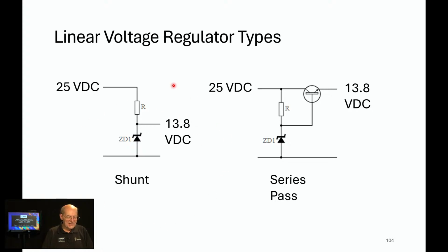Well, yeah, and Kessler's material, he says that, and he's right, for this to work with a 100-watt transceiver, we're talking about a transceiver needing about 25 amps. There is no such thing as a Zener diode that can handle that much power. So this is in very low power applications or in receiver circuits, if you need some regulated voltage, you might see this, but generally speaking, in any kind of a power supply for a transceiver, you will never see this, because Zeners can't handle it.